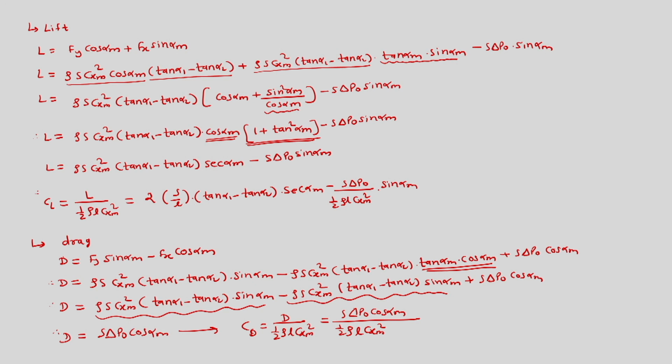So, this is the method by which we can find out the different forces acting on the cascade. Here what we have seen is the different angles associated with a cascade testing or blade design or blade testing, angles like camber angle, air angle, blade angle. So, these are the angles, and once we set these angles, we measure the direction of velocities and we can get the drag and lift, or the Fx and Fy forces acting on the cascade.